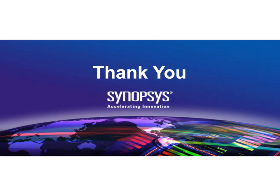All right. And our next question for you, does star ECC perform SEC-DED for multi-bit soft errors? Yes. The star ECC is a programmable solution. While regular ECCs do Hamming code, which is for single correction, as we all know, with star ECC we provided a solution that can do single, double, triple, 4, and it's programmable. So you decide how many bits in a word you want to correct, and it generates the necessary circuitry for that. It has several advantages of pipelining, insertion, and so on.